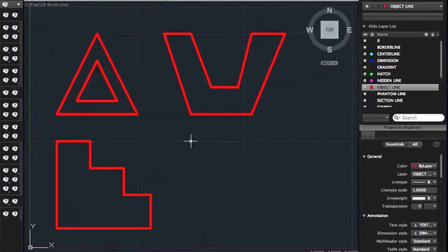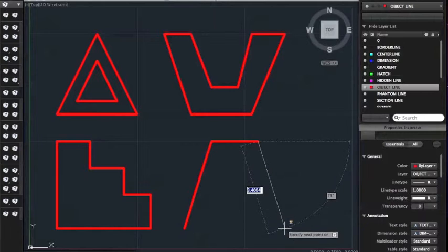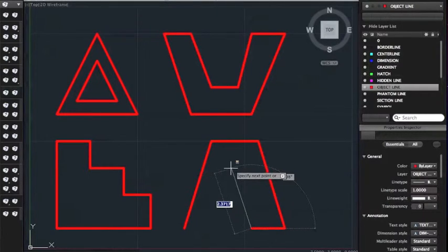Okay, we're going to do the final object. Here it's spacebar to bring the line command back up. First point, hold the shift key down to make the angle. And shift key down again. Here, C, enter will close the object.